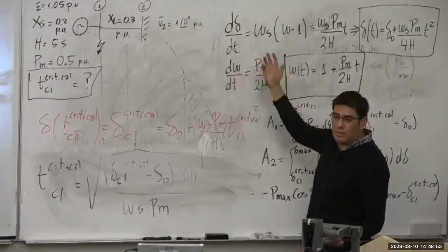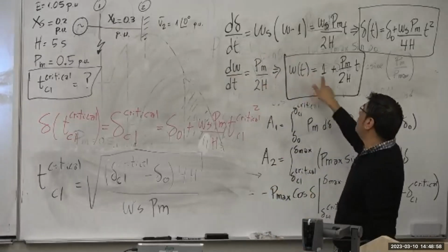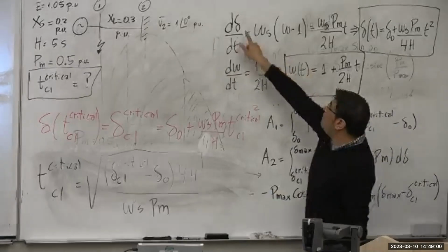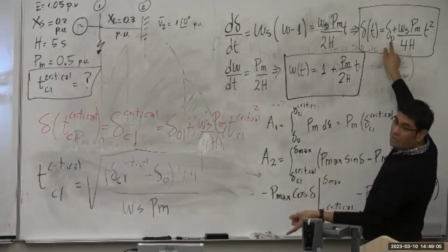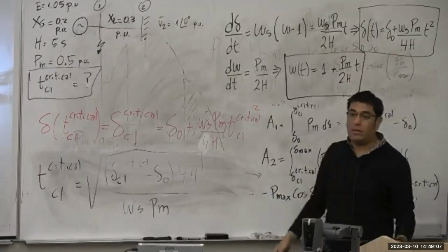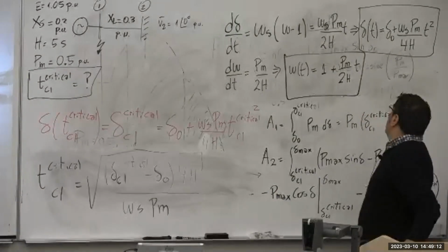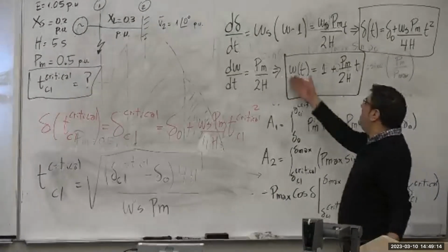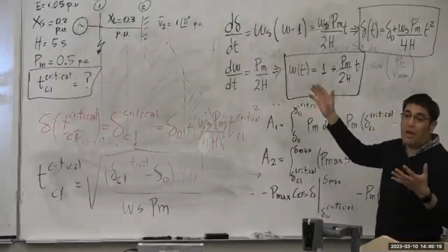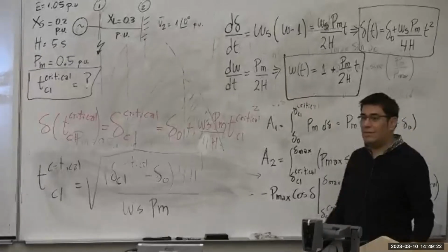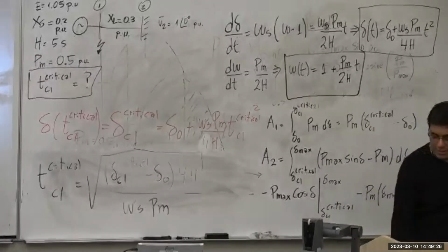The integral will come with a constant. So that's the speed we have at time 0. I see. The same thing will happen here for the angle. We get the integral. This is the angle at time 0. That's the equilibrium point. And so these equations are for the fault period. Yes, that's for the fault period. We can easily calculate it, because it's a short circuit with electrical power equal to 0. So we can choose that to check it. Okay, guys, thank you so much.